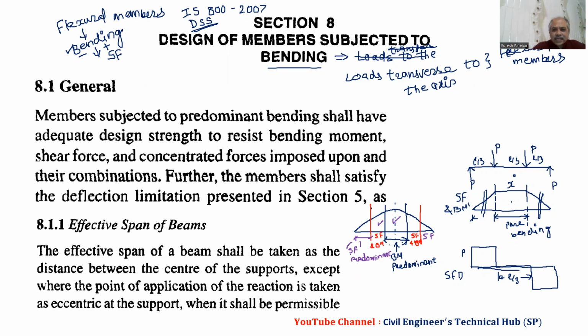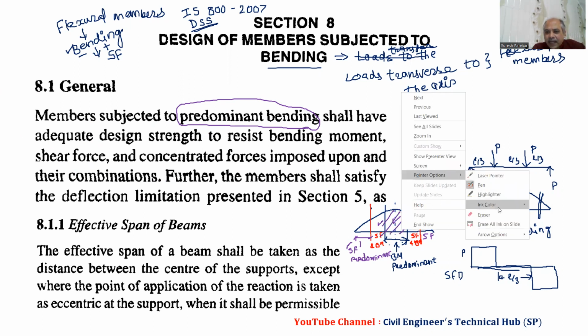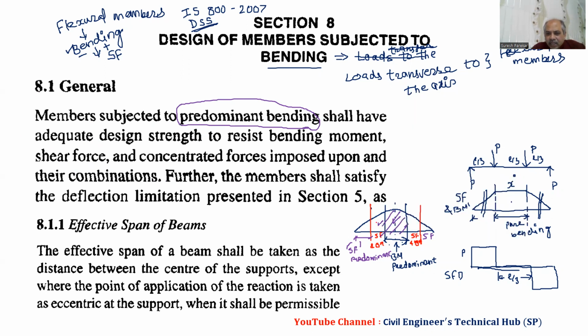Now we go with section 8, which is for flexural members. It is clearly mentioned: members subjected to predominant bending shall have adequate design strength to resist bending moment, shear force, and concentrated forces imposed upon them and their combination. Section 8 is for bending moment predominant. If we go to section 9, which is combined effect, that covers this portion.